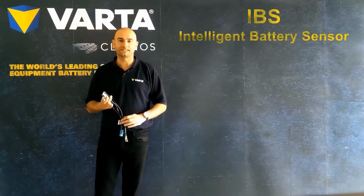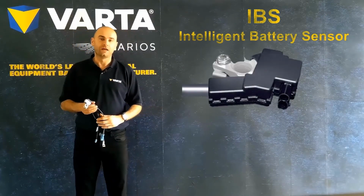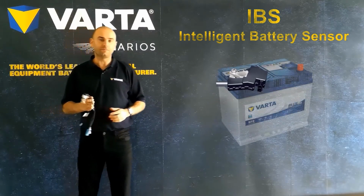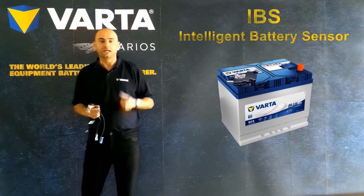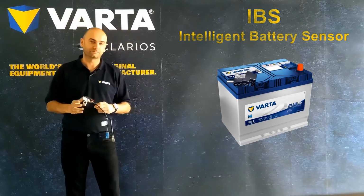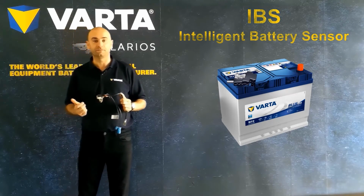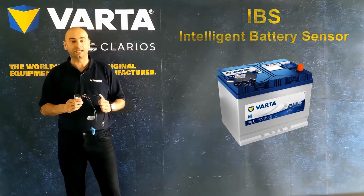The IBS, Intelligent Battery Sensor, is an important part of modern day vehicles. The IBS can be found located on the negative post of the battery, not the positive post, because it's on the load path of the circuit. It can then see the load drawn on the battery correctly. As consumers are active, the IBS monitors the amp drawn from the battery and will alter the charging profile or start the engine if needed.